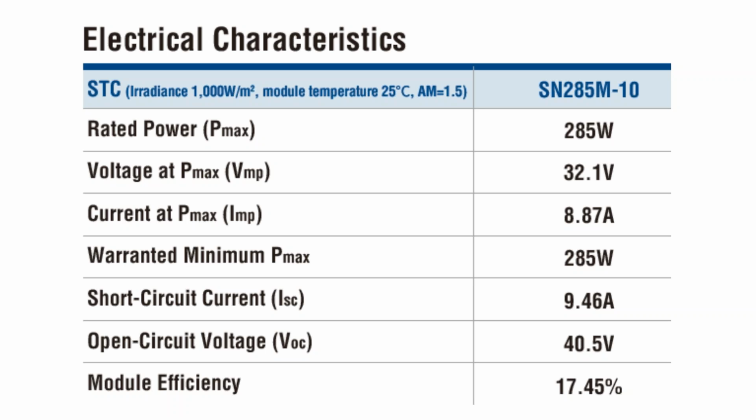Same with voltage. So, you might be hand performing some calculations and get confused about, well, am I supposed to do my sizing based off what the array is actually operating at in terms of voltage, or what its maximum voltage is going to be? You use the VOC and the ISC, the open circuit voltage and the short circuit current, when performing your safety calculations.